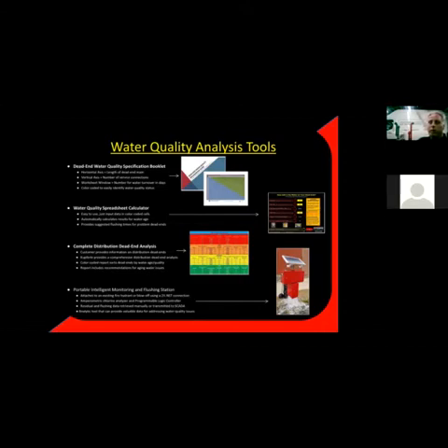The device will turn on when it comes to the sampling time. It will flush some water. It will get a fresh flow of water in the flow cell. It'll take that sample. If I'm below 1.5, it'll flush the exact amount of water until it hits the 2.0. It collects data. It transmits the data on the water quality for both chlorine and PSI and pH and temperature and so on, right from the station to a phone, a SCADA system, a laptop, wherever you want to send the data. It has a wireless gateway in the device itself where it can transmit the data. So it'll hold those parameters for you over time.